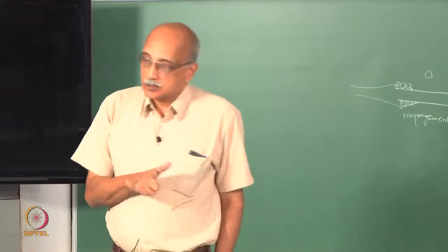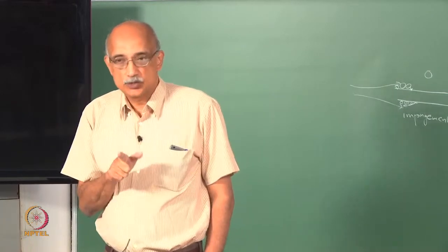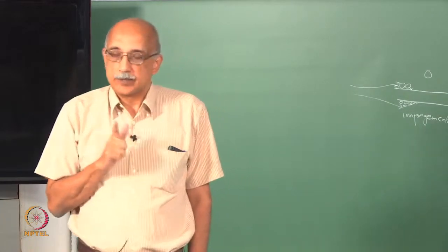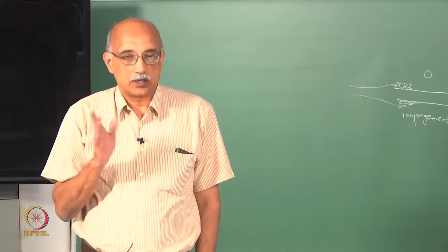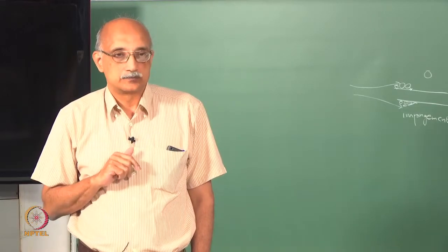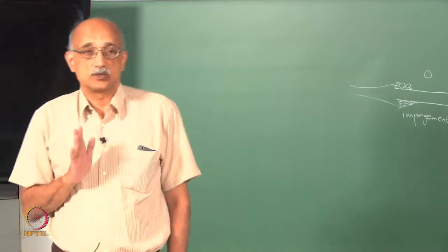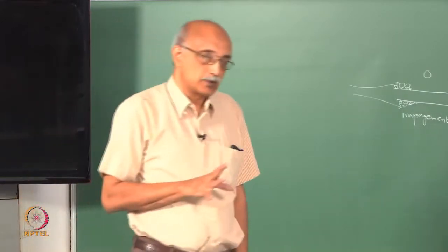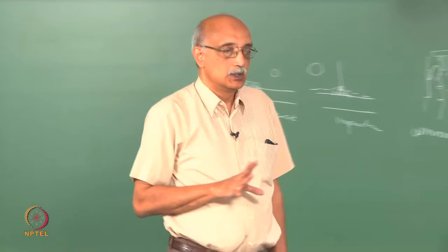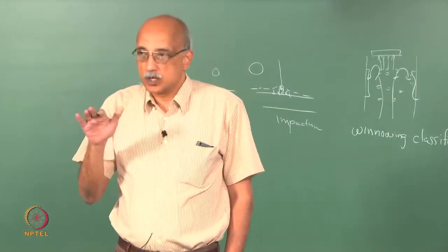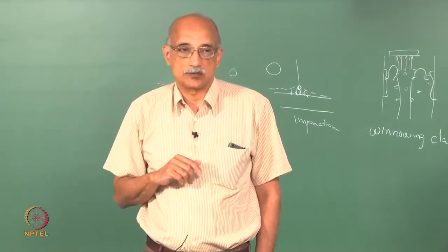The limitation again is, in an optical microscope the resolution is better than the human eye, but it is still only of the order of about 5 to 10 microns. So, you really do not want to rely on an optical microscope if you are trying to size particles that are smaller than 5 microns roughly.